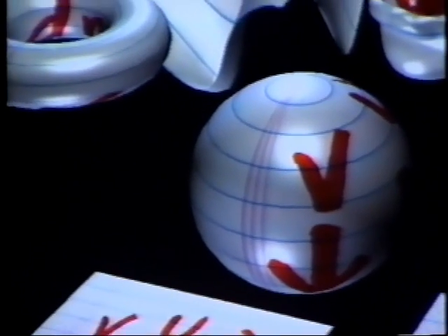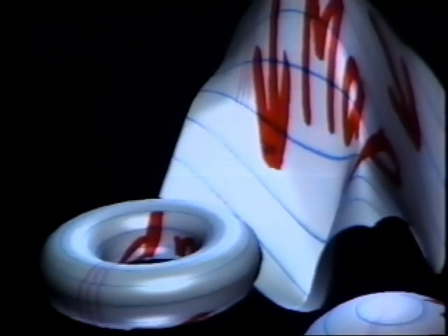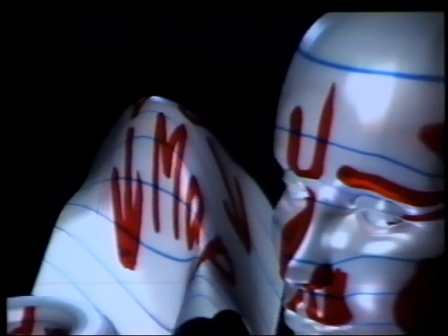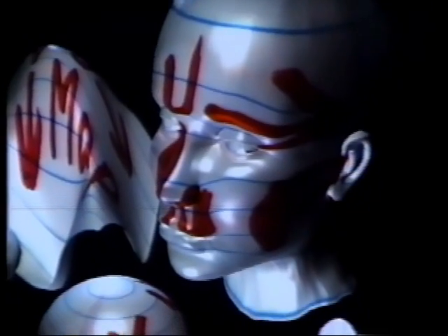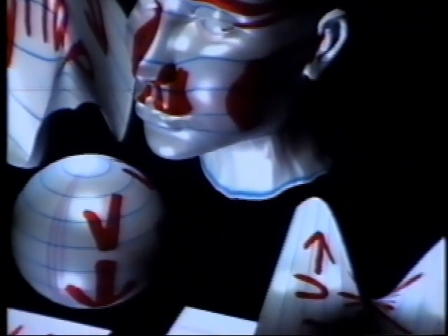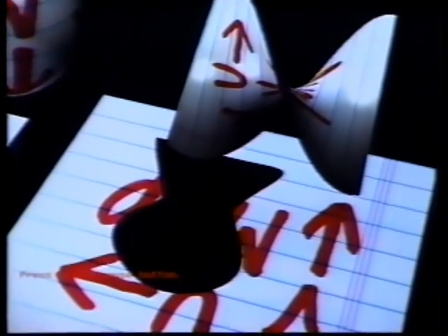When you're planning any surface model, try to imagine how you would bend or wrap a single piece of paper into that shape. No matter how it's stretched or twisted, it always has its top, bottom, left, and right, and still has its rule lines running in the U direction. A trim has no effect on the mapping or the parameterization, and only hides a portion of the map.